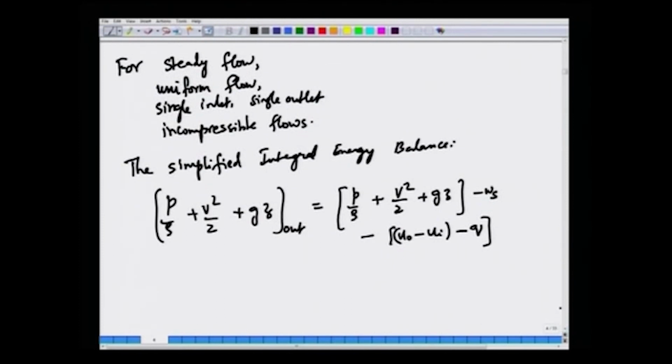So, what we are saying essentially is that for an incompressible fluid, the heat transferred can affect only the internal energy. For example, the heat that you are putting in cannot go into increasing any of these, that is why these two terms are clubbed together. But suppose for the moment that the CV is adiabatic, that is, Q is 0, no heat transfer to or from the fluid.